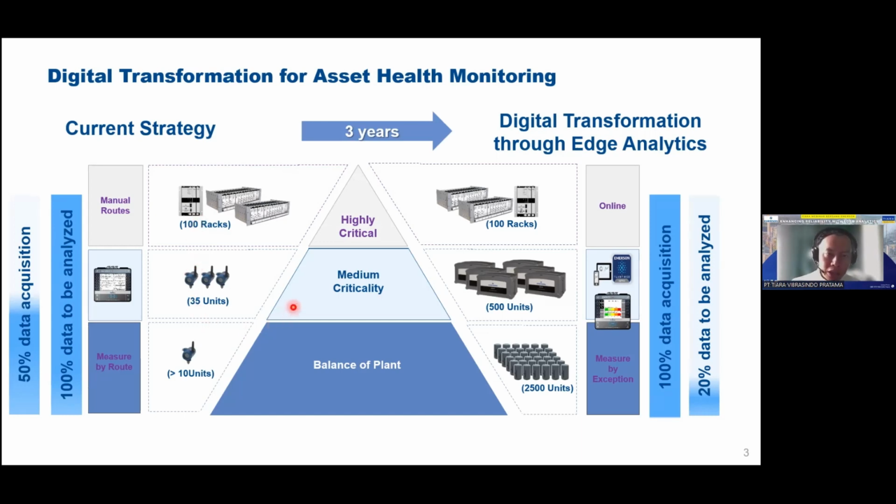And the majority of the machines in the plants, what we call those with medium criticality or less, or essential assets, or some people say balance of plant. Most of the time, these are not monitored online, but instead you do your routine data collection. Using your portable analyzer, you can collect data once every 2-3 months and repeat the whole process.